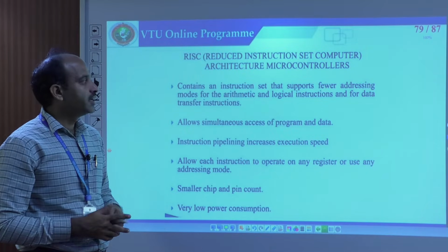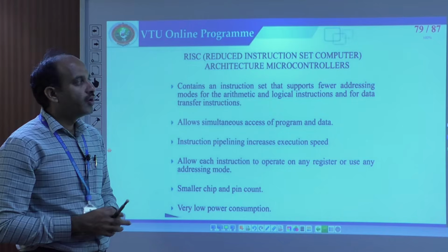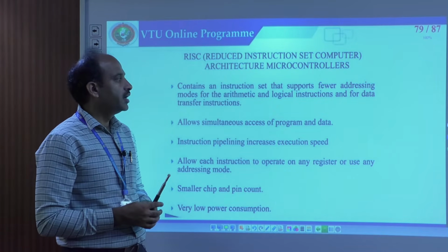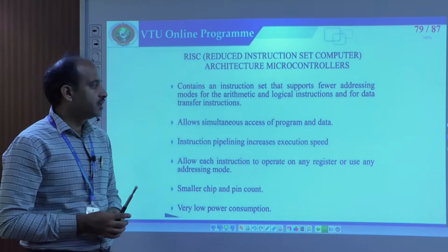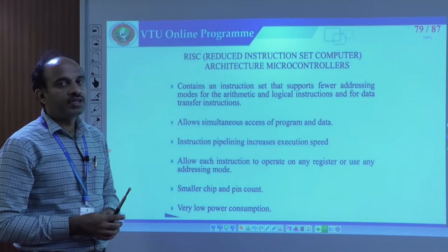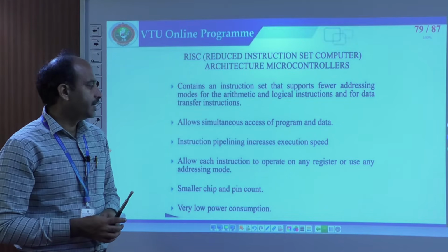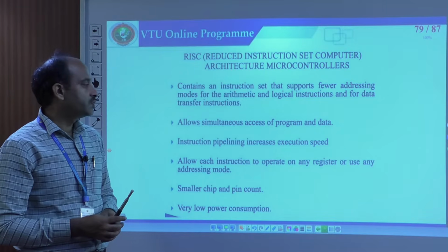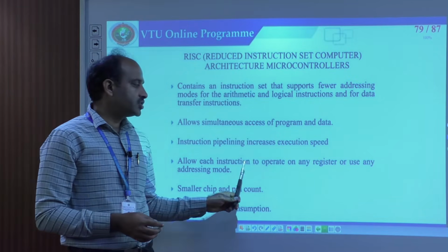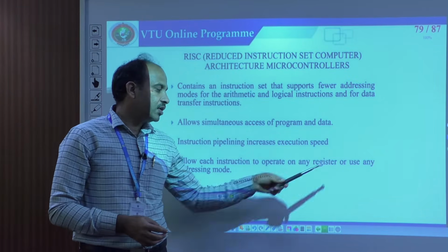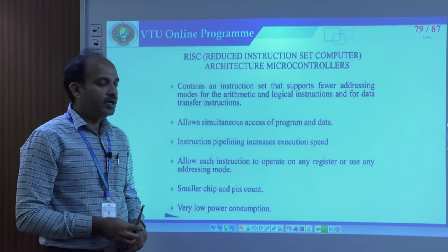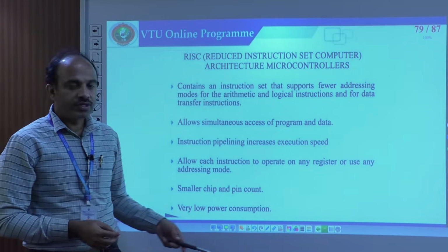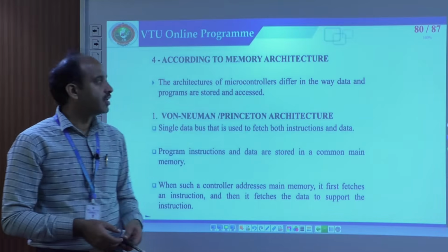And the RISC contains instructions that support fewer addressing modes for arithmetic and logical instructions and data transfer instructions, and it allows simultaneous access of the program and the data. Instructions will be pipelined, so increasing the execution speed, and it allows each instruction to operate on any register or use any addressing mode. The chip pin count will be smaller, and the power consumption is very low.